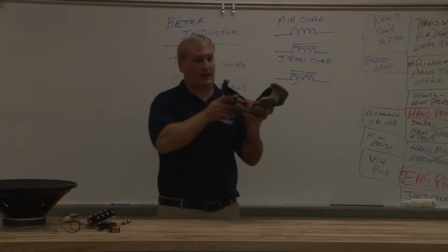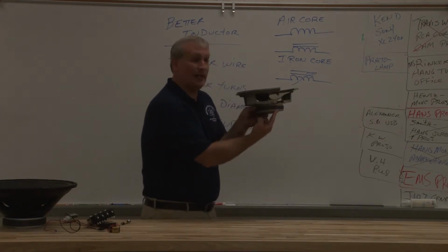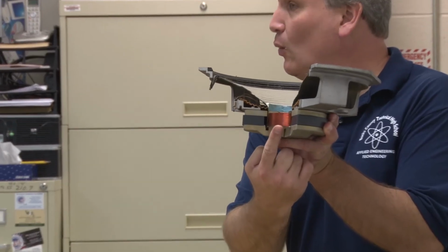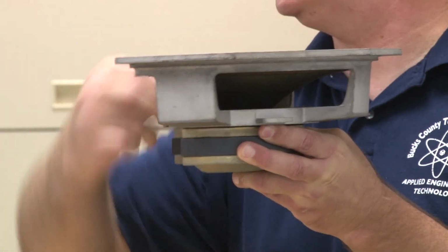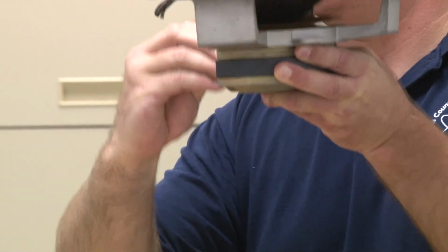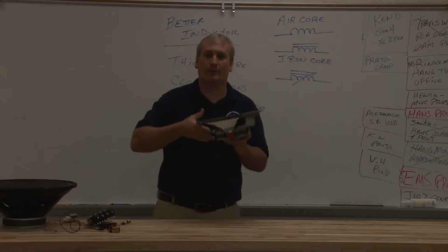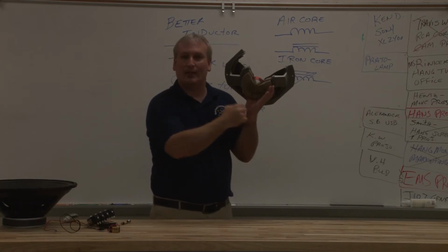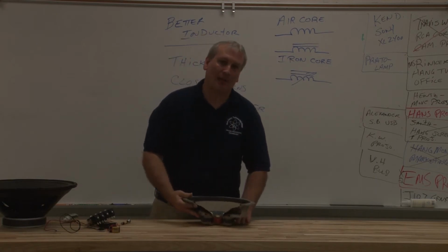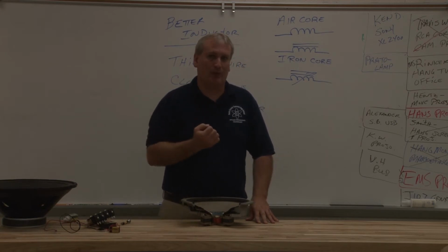Okay, now here's what happens in a speaker. I'll send this around in a minute. We have a voice coil. They call it a voice coil. Here's another. It's just a coil of wire, another inductor. The inductor is glued to the cone. So when I move the inductor, the cone moves up and down. So what makes the inductor move? Well, around the inductor is this magnet. So if I have an inductor and voltage and current flows through the inductor, a magnetic field builds up.